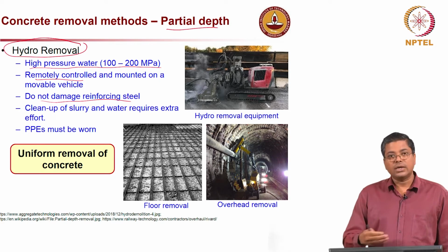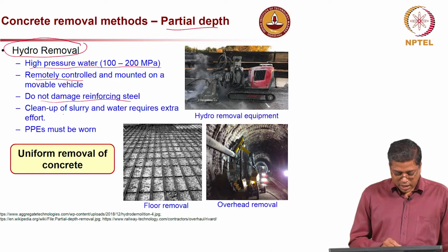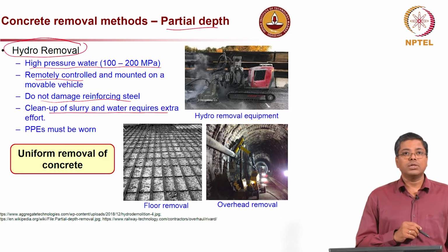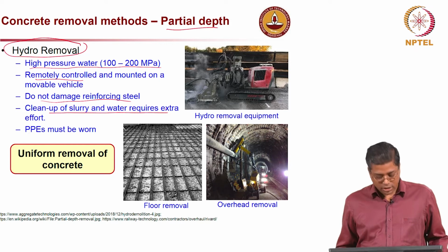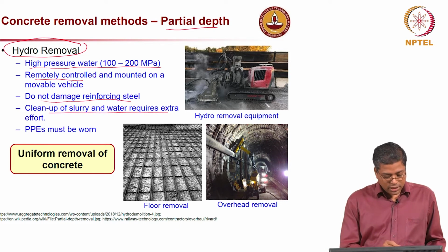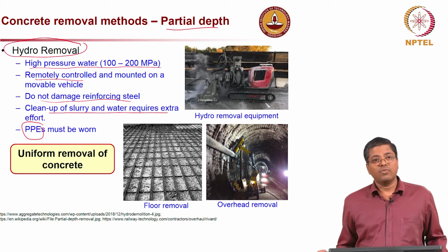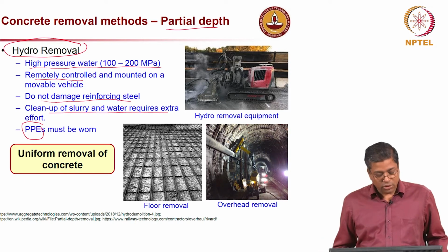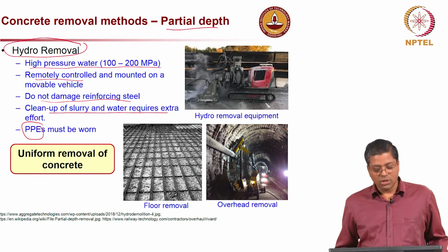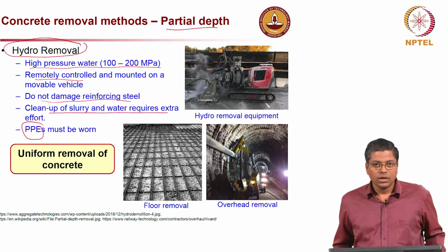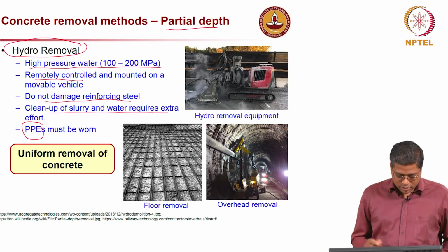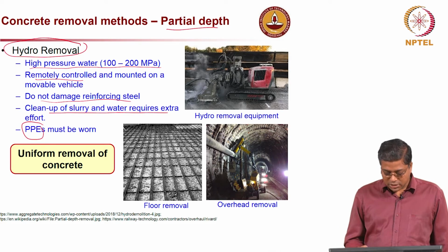The concrete is removed layer by layer, and one negative thing is that we have to clean up all the slurry, which sometimes requires extra effort to clear from the site. Again, because you are talking about very high water pressure, PPEs must be worn. Imagine you are cutting concrete. If that water jet hits your skin, it is going to cut the skin too, right? So that is very important. Special protective gear must be worn.